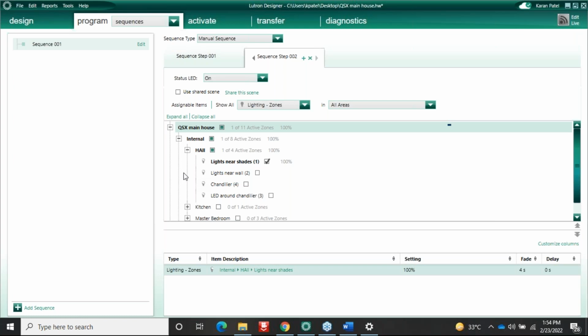Gaurav Bhatt asked the question: do we have the hold function on the Pico? No, Pico has only 2 functions, single action and toggle. There is no double tap, no press and hold, and no dual action. Because of the Pico battery, if you have the press and hold function, it will definitely drain the battery more rapidly. So we give only single action toggle in the Pico.